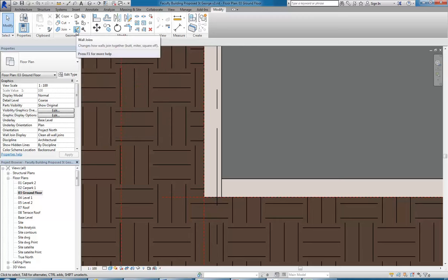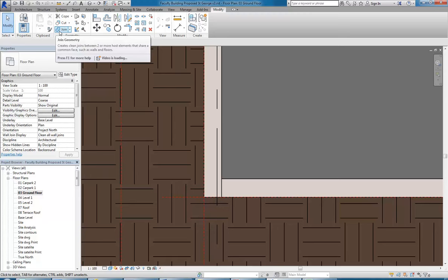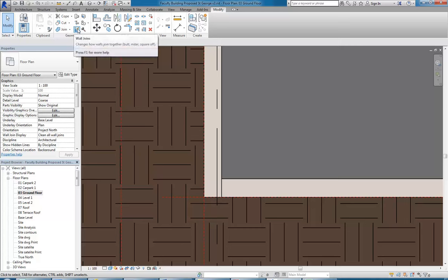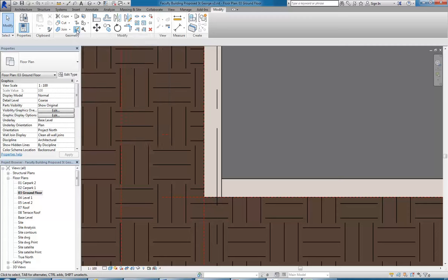So this is a feature of Revit. Walls particularly have automatic joins. So they connect automatically in a way that's predefined. Other things in Revit are joined automatically as well, but you've got a bit more control over that because you're generally using this join option to join geometry together. So, just right click on the circle, disallow join, yes. I'm going to look at that in a second. But so this is additional to that. So when you're doing that, you're overriding all of the joins. But this here is using the automatic joins, and there's still a great option using automatic joins.